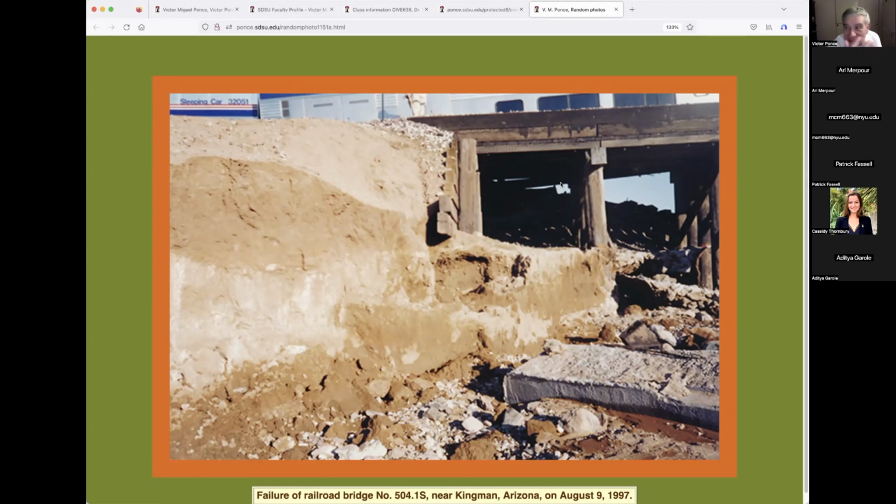In design of engineering, there's forecast, and then there's hindcast, and there's actually design. Those are 3 different things, by the way. The forecasting is when you are forecasting that something's going to happen. That's a very difficult thing to do because you don't know when and how it's going to rain. The hindcast is what we're doing in here. Basically, the bridge already failed, and we're going in there and trying to figure it out, a sort of post-mortem. Why is it that it failed, right? There's a hindcast. The design is just for design. The design does not consider that there's going to be a flood over there or anything. It just goes in there and says, what's the frequency according to established standards? And we're going to size up the structure in one way or the other.